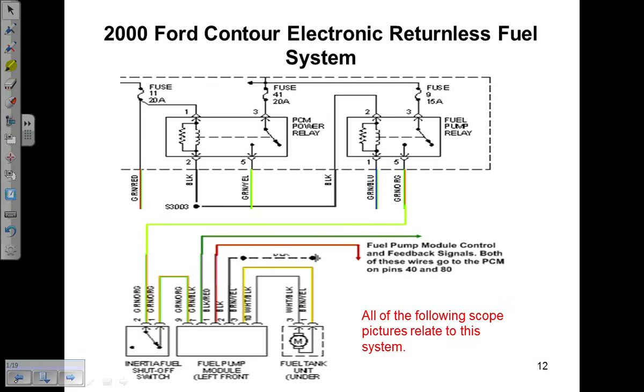And it isn't just as simple as low fuel pressure or no fuel pressure, oh, let's put a pump in the car. Granted, maybe 80, 85, 90% of the time when you have low or no fuel pressure, you need a pump, or a plugged up filter. But there's that 15, 20% where you're going to run into electrical problems. And truthfully, doing diagnostic work, being 80%, 85% is not good enough. You need to be in the upper 90s.